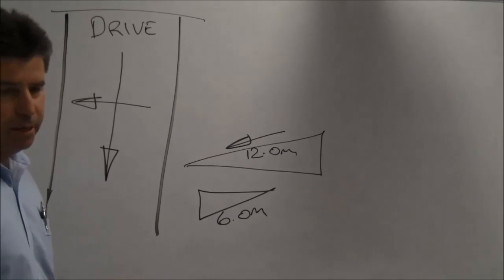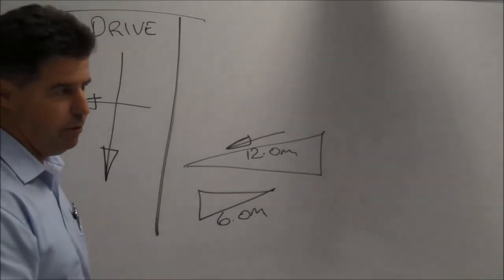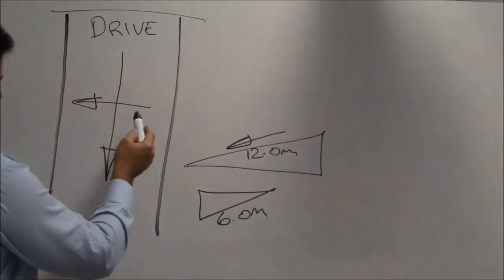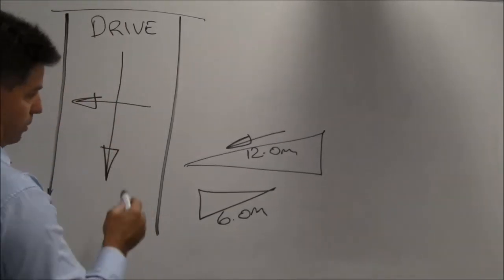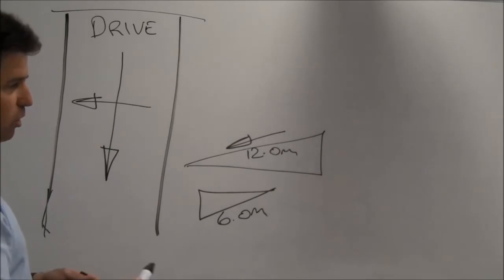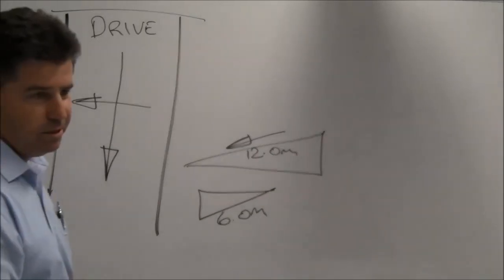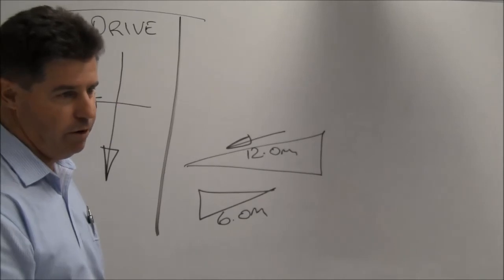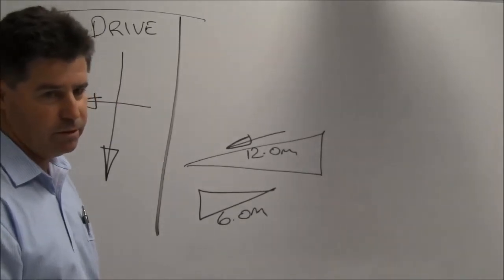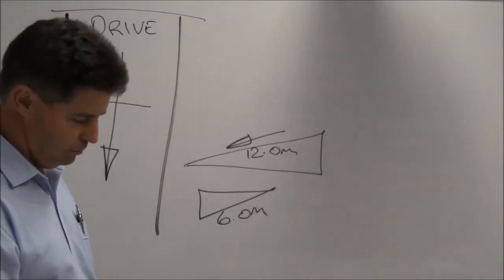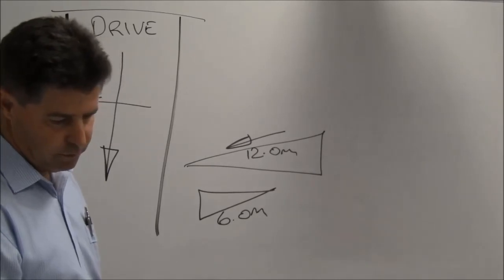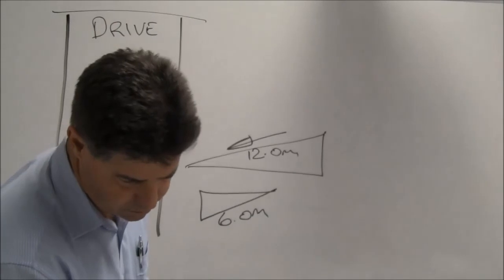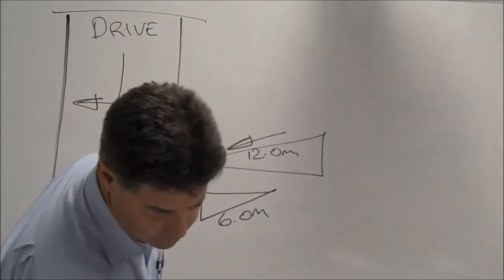So that becomes, again, it's just Manning's equation, so that becomes our area. That's all we're doing. And then the rest of it depends if it's concrete, bitumen, stones, grass, depends what they're building their driveway out of. Different flow rates for different surfaces. And then the next page talks about 300 freeboard.